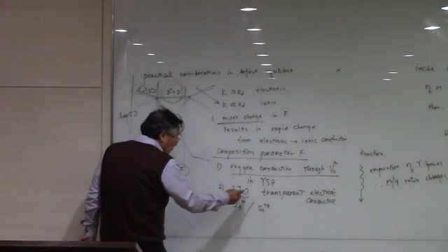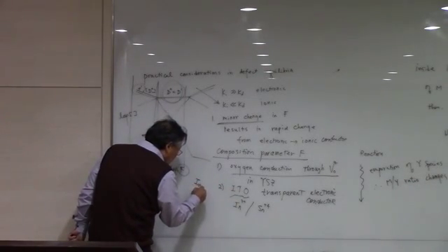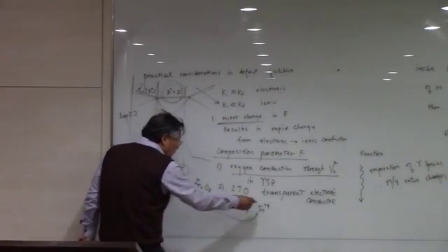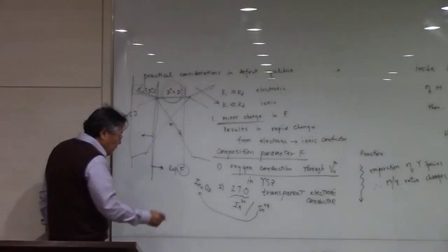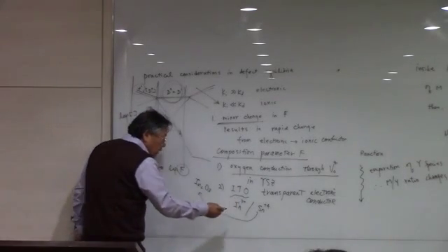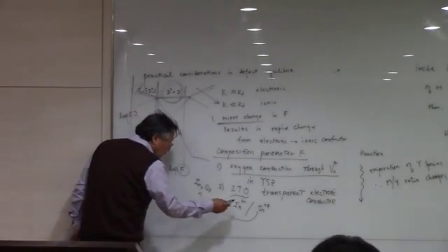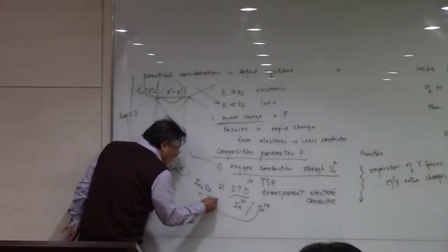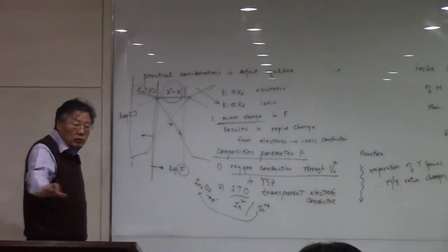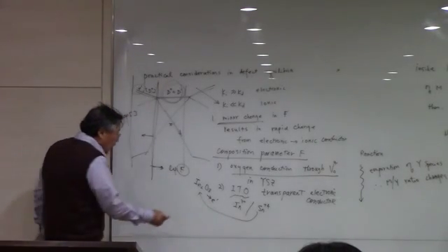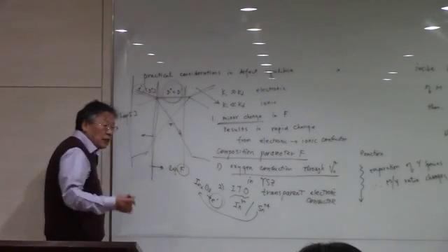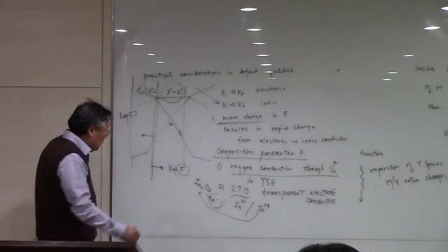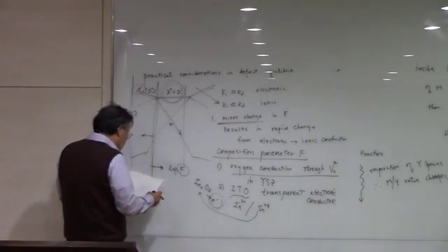Okay, indium oxide is In2O3, and some of the indium is going to be replaced with the 4 plus, and then 3 plus is replaced with a 4 plus, so that every single replacement will render 1 electron to neutralize the system. And that electron is used as a free carrier for the conductors. And that is what the ITO is. The same thing happens in the zinc oxide.